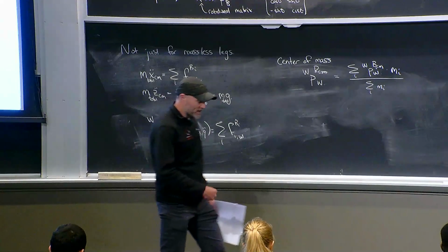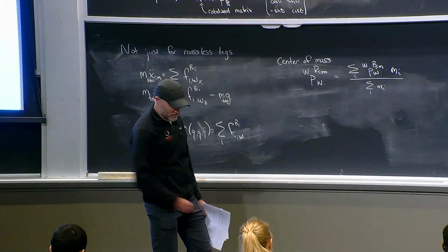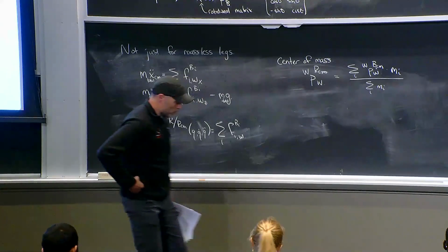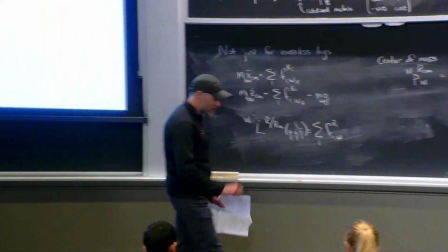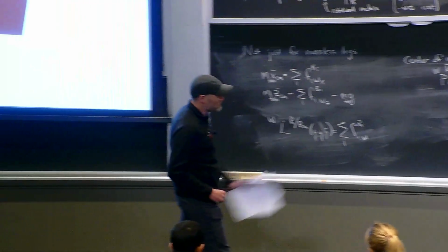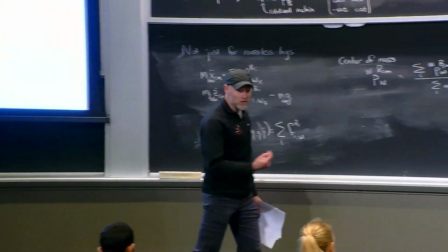So if I control the kinematics of my center of mass, then I'm actually controlling my ground reaction forces. Okay. So when you don't worry about impacts and you don't have to worry about uncertainty in the ground, position control seems to be enough because of this very simple relationship.